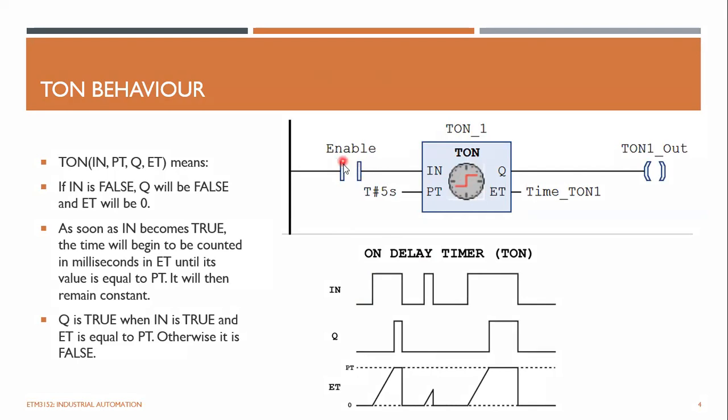The normally open contact is now closed, and this IN pin gets high, and then the set elapsed time is just starting, it is counting. The time is now counting, and its current time is updating, and then it reaches 5 seconds. Right? When the time reaches 5 seconds, the output Q1 will be set to high. Before that, the output is always 0.